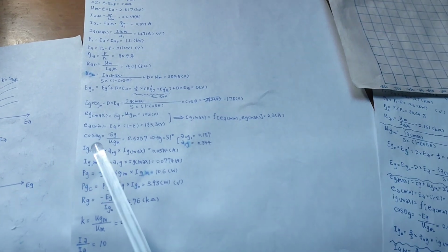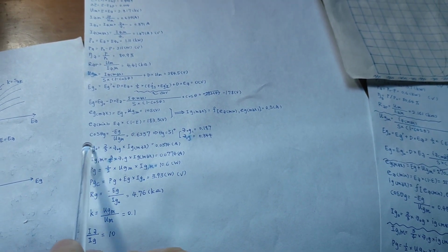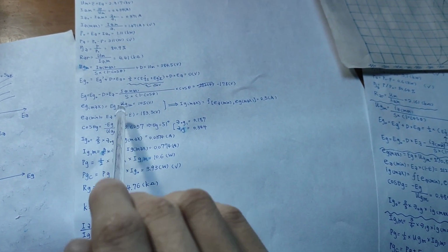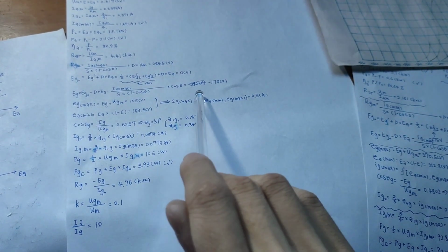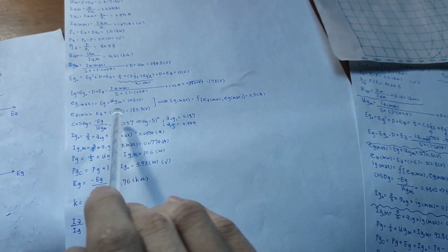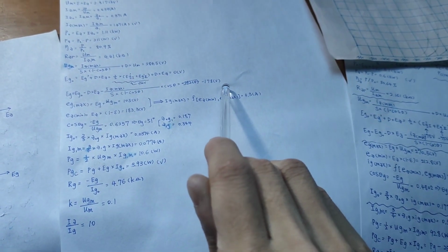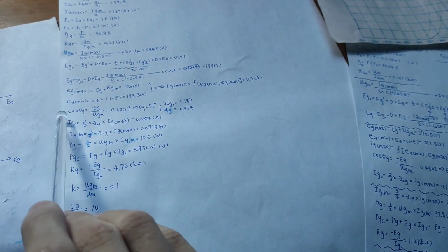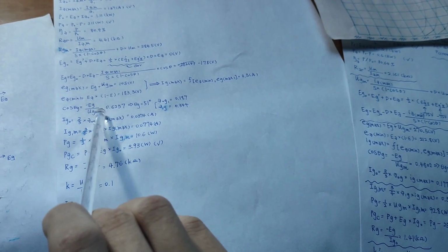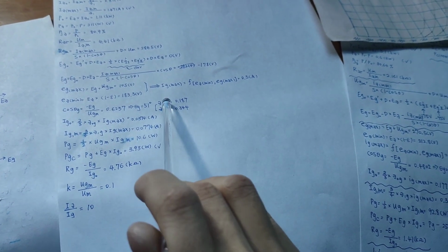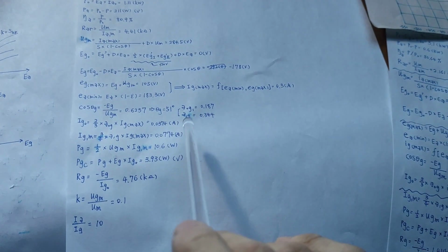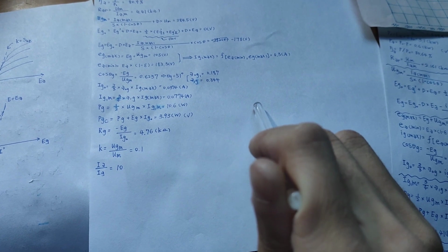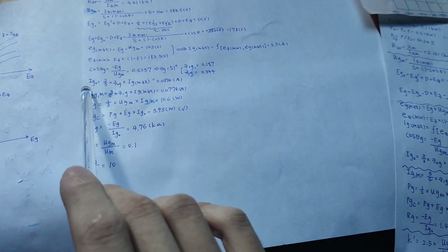So we need to do another analysis here to use this value. The grid voltage minus the grid voltage you see here. Because this is a -1, so we want to get a positive value. Use this one divided by the voltage swing, half of the voltage swing of the grid, and you can get a cosine value. And refer to a table, we can get these two constants, which is actually the same meaning as these values, but it is for analyzing the grid waveform,